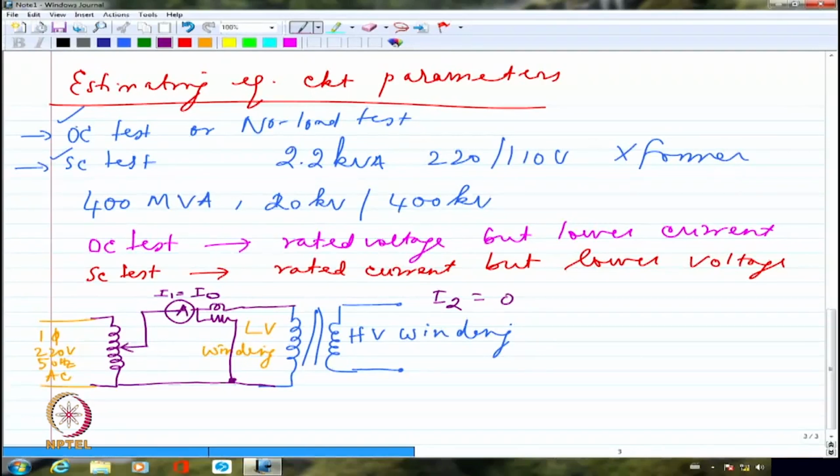And as we know, the no load current of a transformer is really small because of the no load losses being small and also the permeability of the core being very high. So I can say that even if I consider the series resistance of the transformer, which I may call R1 and X1, the series resistance loss is going to be really small. Let's take the quantities. If I say that at 100% load, I1 square R1 is 100 watts, let's say.